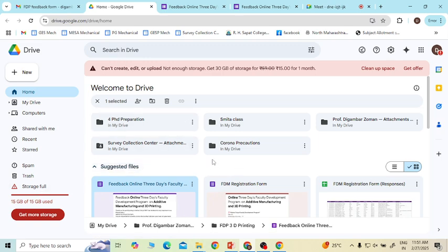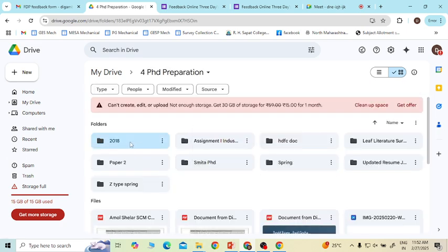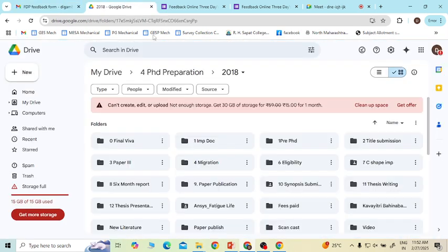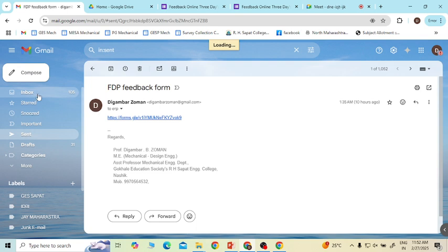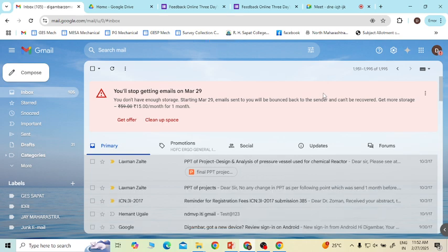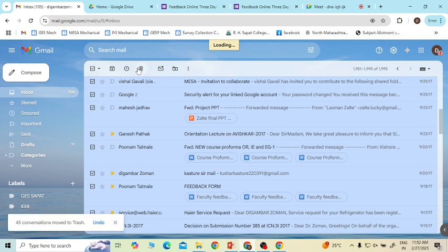This categorization of manufacturing processes we have already addressed. In the afternoon session, Professor Ravi Gite will be detailing all these processes, based on powder, liquid, and solid. For powder, you can see SLS is there. In case of solid, you have binding and laminated. Laminated object manufacturing is layer by layer, where one lamina, one sheet, is one layer. Here you can have photo masking and likewise. This is the classification of layered manufacturing or additive manufacturing, depending on whether the raw material is in powder, liquid, or solid form, and you have to use the corresponding method for manufacturing.